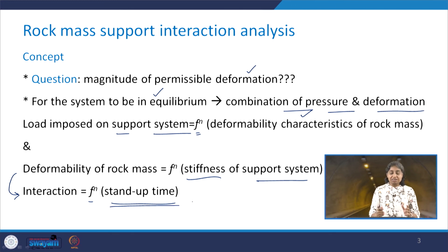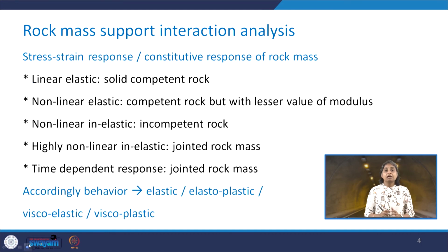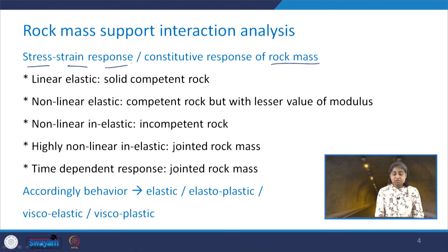So, we have discussed what the stand up time is a couple of times in some of our earlier classes. Now, before I go further, let us try to understand first the behavior of the rock mass and then the behavior of the support system. Then we will try to understand their interaction phenomena. So, as far as the rock mass is concerned, its material behavior will be given by stress strain response, or we can call these the constitutive response of the rock mass.